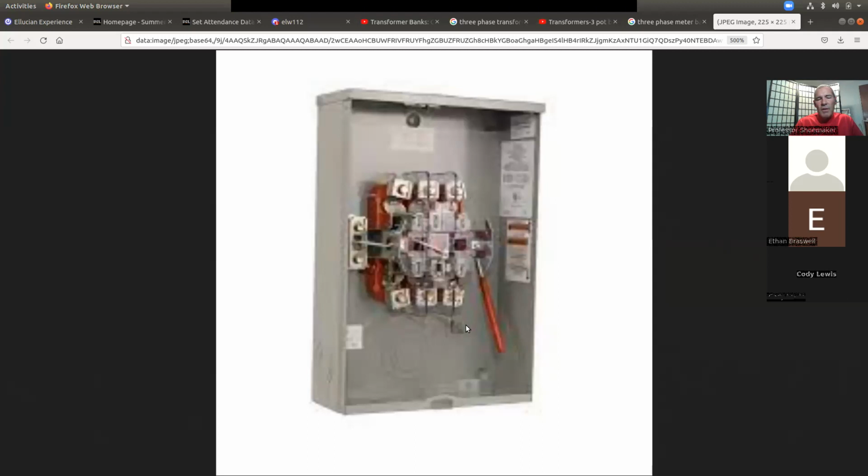Your electrician, on the other hand, who was the person that knew about BOY? I did. Okay. He's going to wire B, O, and Y always on the right-hand side. Your electrician knows now that the high leg is also on this side. He won't mix it up either because he's got his mark BOY far right. If you put the high leg, say your high leg's 208, in a 120 lug, you're going to burn up people's equipment and stuff inside. High leg always goes far right.